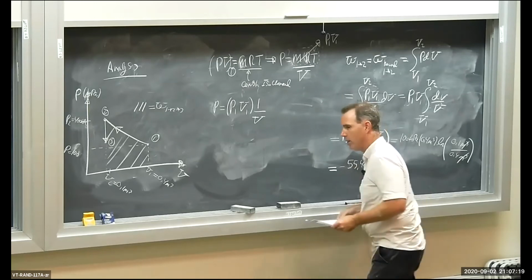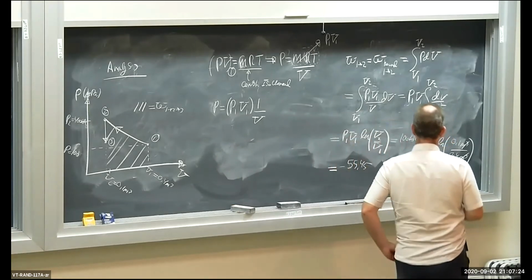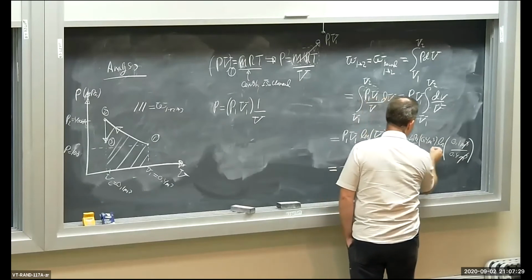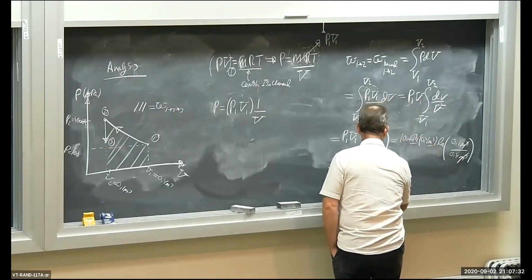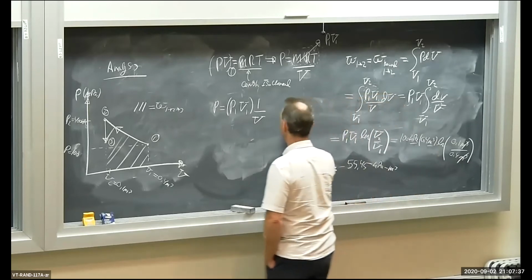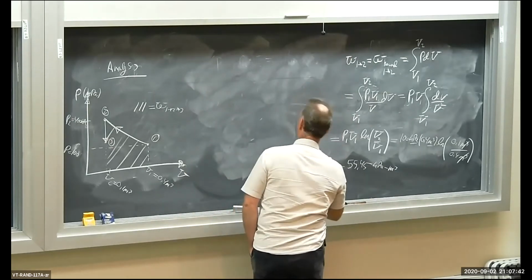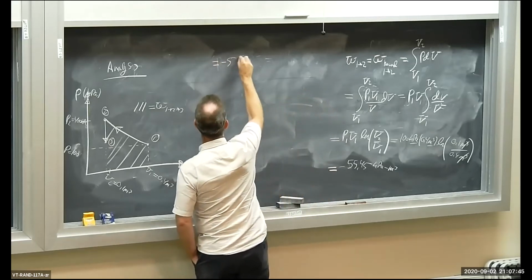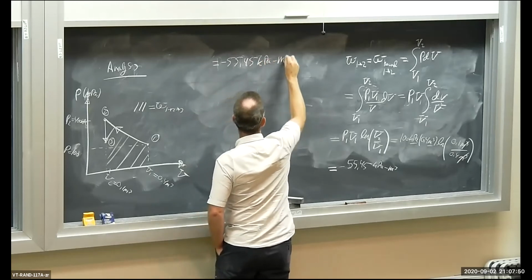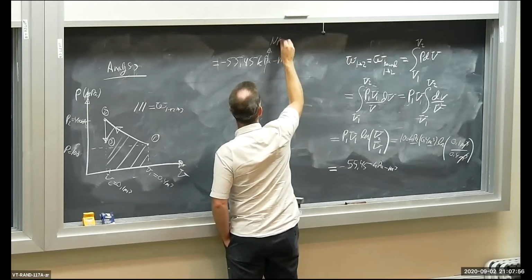55.45. Now, what's my unit there? Well, I've got a kilopascal and a cubic meter: kPa cubic meter. I'm starting to run out of space here, so I'm going to go right over here. So I have negative 55.45 kilopascal cubic meter. Well, a pascal is a Newton per meter squared.